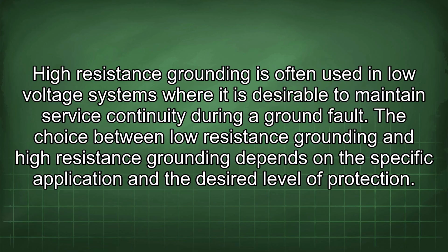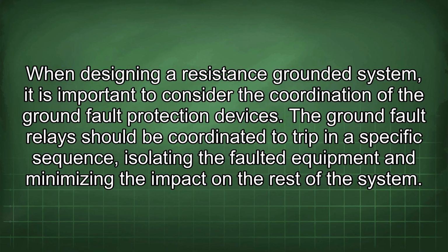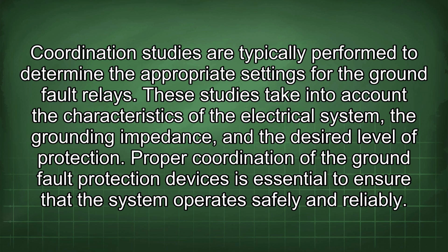When designing a resistance grounded system, it is important to consider the coordination of the ground fault protection devices. The ground fault relays should be coordinated to trip in a specific sequence, isolating the faulted equipment and minimizing the impact on the rest of the system. Coordination studies are typically performed to determine the appropriate settings for the ground fault relays. These studies take into account the characteristics of the electrical system, the grounding impedance, and the desired level of protection. Proper coordination of the ground fault protection devices is essential to ensure that the system operates safely and reliably.